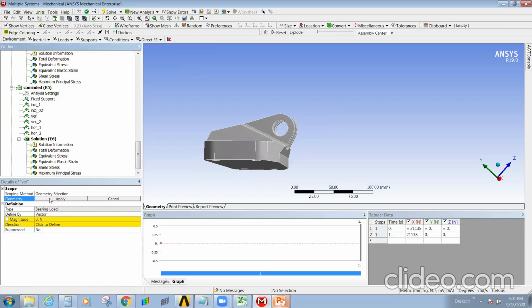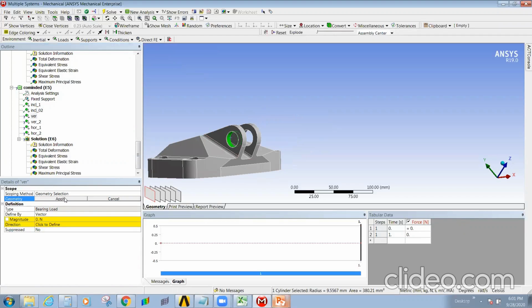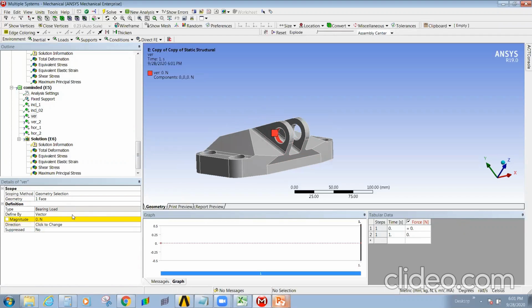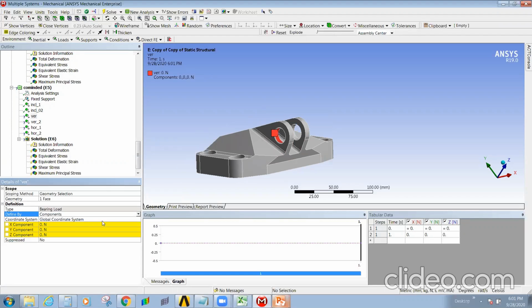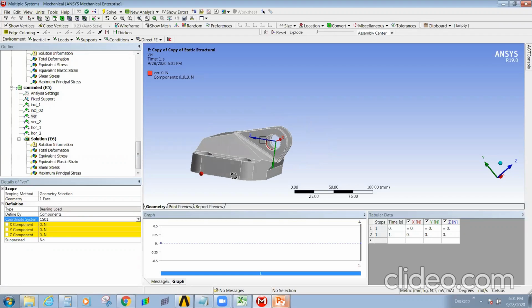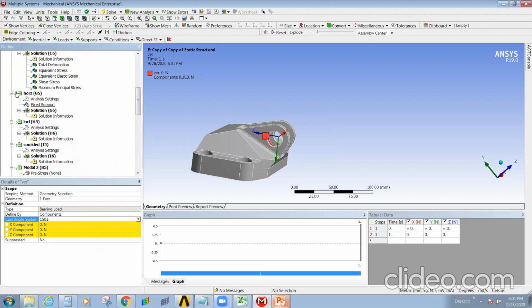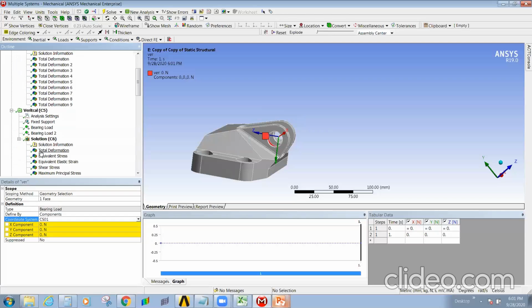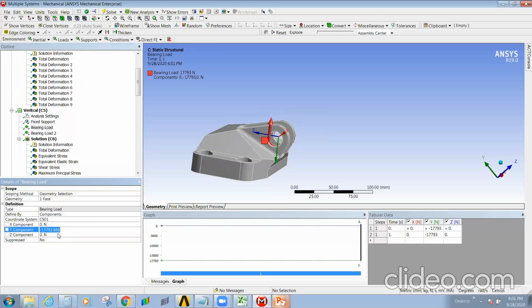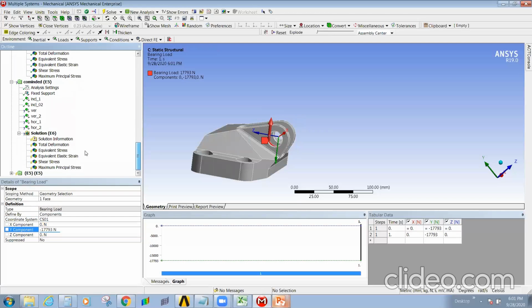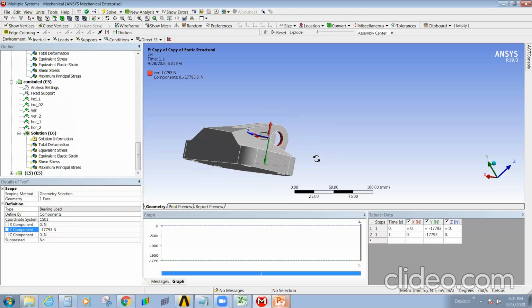So for vertical, you need to select which face, or which lug, you want to apply to, and then for vector, remove that and make it as coordinate component, then global to CS01. Now the value, which value it will be, your first vertical value. So I'll go back, the initial one, so negative y, okay. Similarly, now it is applied vertical.